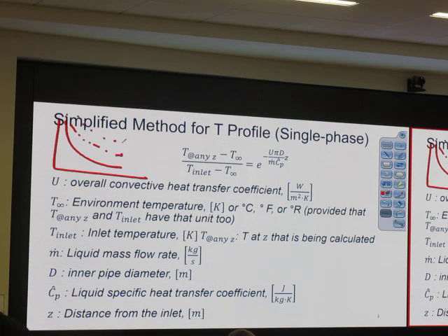The important thing with this lowest possible temperature profile is that it is the worst case for the pressure drop calculation. When the temperature is low, viscosity is high, and when viscosity is high, we get the maximum possible pressure loss. So if we have a simulator doing a very good job, we can double check. If the simulator gets any temperature lower than what we say, it is wrong.